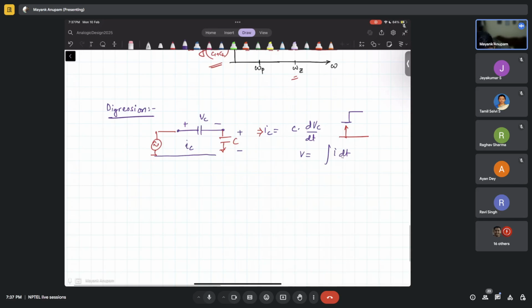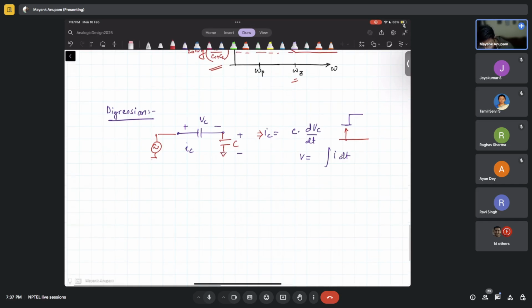here a complete circuit path is actually completed by only capacitors, right? And the voltage source. So whenever you see something of this kind, you should expect that there will be a zero somewhere, and that is what I'm coming to next.